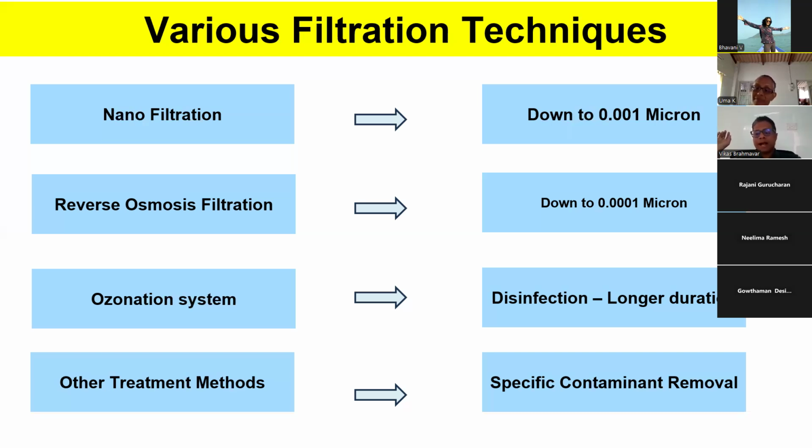It removes good, bad, ugly, every sort of contamination down to 0.0001. It removes everything almost equally. That is why it is commercially available easily in the market. Because when you have balanced water coming in, this will give almost balanced water going out. So it will do maximum filtration, but there are a lot of problems in terms of wastewater.